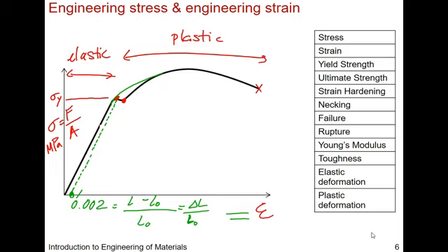Okay, so let me delete that and be a little bit more careful. There you go. Okay. So that's where we define the yield strength, because one could argue, where along this curve should you stop? Should you count what the yield strength is? We've just said, okay, if the strain is at 0.002, you extrapolate that, and that's going to be your yield strength. That's just the convention in terms of defining the yield strength and where that curve actually is.